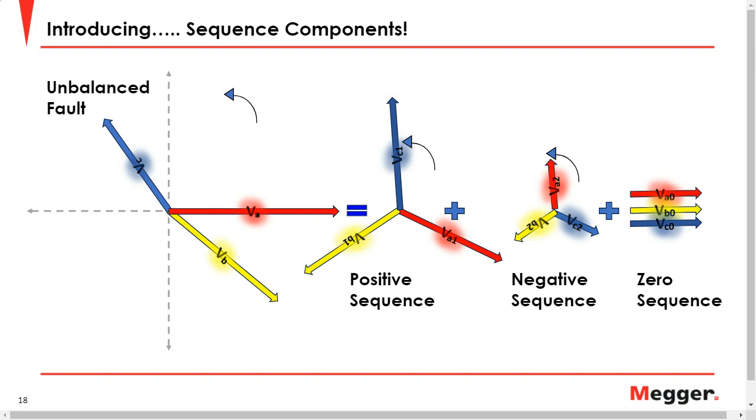In the zero sequence elements, the phase angle of the three phase components is the same, right? Now, when you have a triple harmonic, or any harmonic really, you have to realize that the phase angle of the harmonic is multiplied by the harmonic number, the harmonic index.